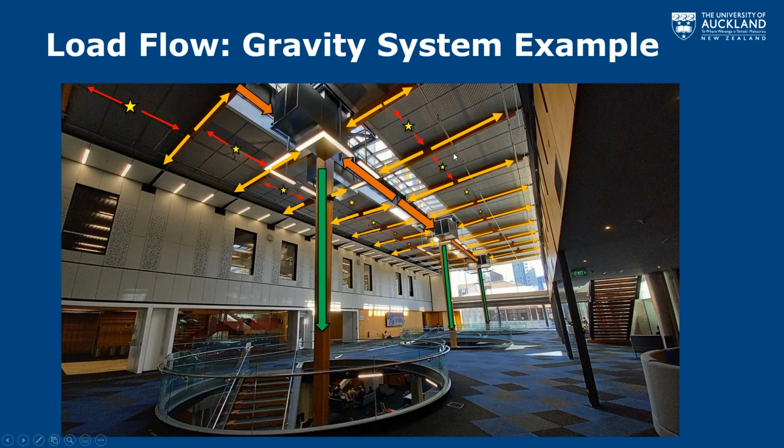And so that should hopefully make some intuitive sense where, as we're moving the load through, we need to make sure that we can account and provide a load path which can support that. And you can think of this again analogous to water flow in a pipe, where if you've got a pipe here, well, you have water moving through each of this. You can't constrict down one end of the pipe that is further downstream, or else it's not going to be able to carry all of that water. So instead of thinking of sizes of pipes, you can think of capacity of the members and the connections which connect those members. So that is an overview of load flow.